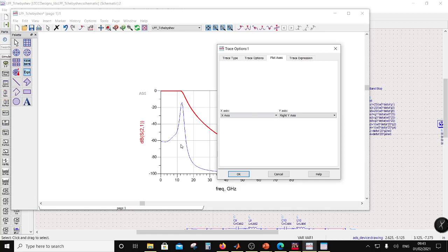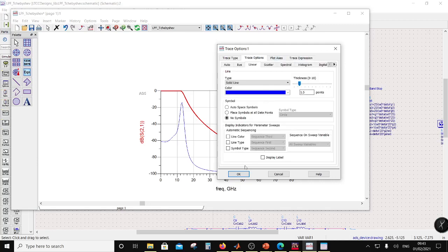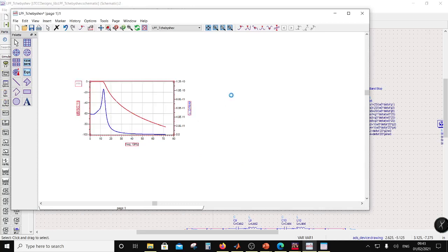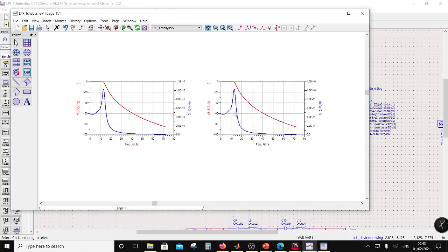So this is suitable for the passband characteristics you are desiring. Otherwise, you might have to do an all pass phase equalizer, which I'm not talking about here, but in a communication system, if you want to make the phase also flat, you might have to do an all pass filter, which is basically adjusting the phase equalization. So I'm not going to cover that in here. Okay, so that's that. Now I can do the same thing for the, so that will be 4-3.